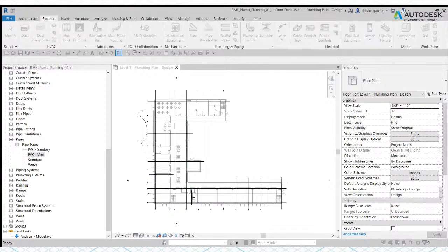Okay. So aside from that, you can also consider going to the conversion. Okay, so we are working on the sanitary planning. So what I'm gonna do is I'm gonna change the system here because we have several systems, right? So we have hydronic, we have the sanitary domestic, we have the fire protection. So we are working on the sanitary. So I'm gonna select the sanitary here. And then after that, you need to specify what is the sanitary pipe that you want when you create your layout. So I'm going to change the pipe type here.